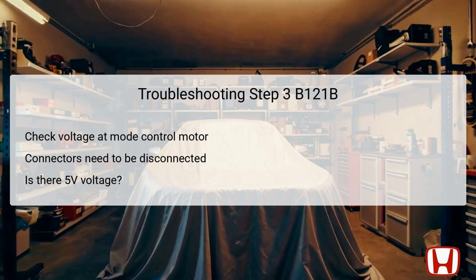If you find that there is a 5-volt reading, it confirms that the power is reaching the mode control motor circuit as intended. Should the voltage not be present, this points to a potential issue further down the circuit that needs addressing, initiating a move to the following step for further diagnostics.